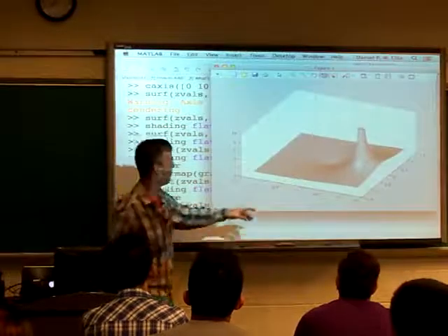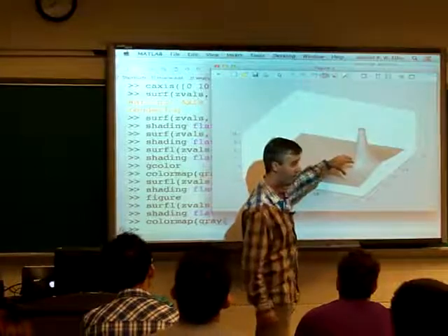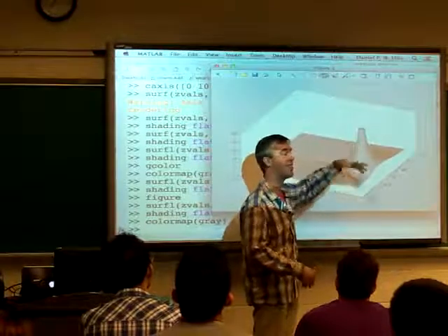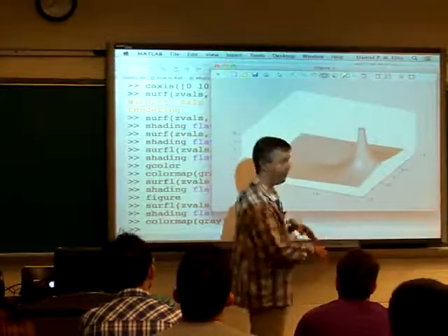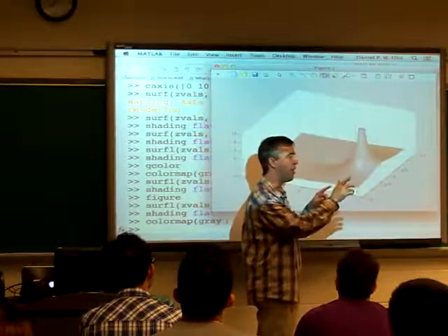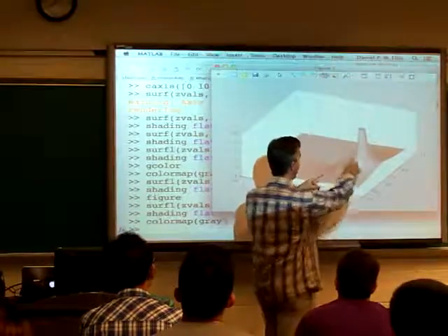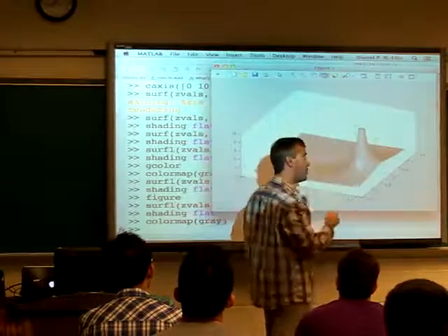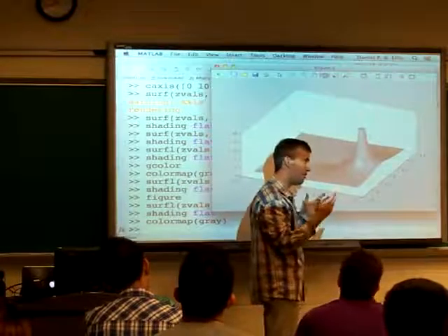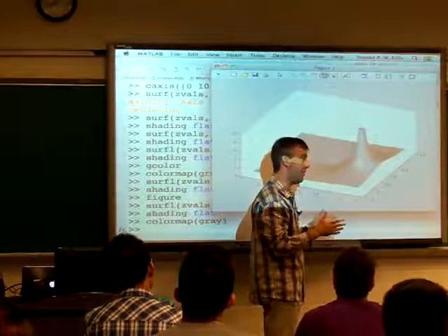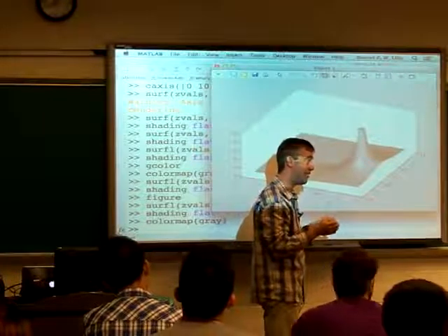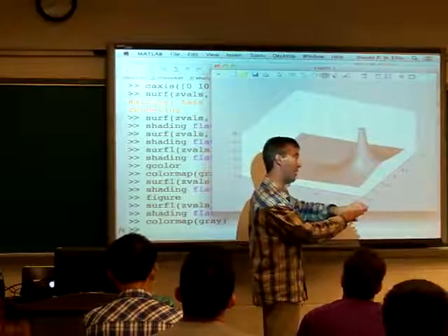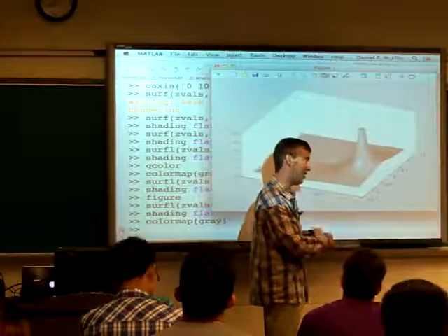It's just that outside of the region of convergence, the inner circle, 1 over 1 minus lambda z to the minus 1 continues to have a nice, continuous, well-behaved function, but the z transform blows up. And the other function, which I haven't plotted, would be this interior part and then blowing up everywhere outside. So you see the two, g1 of z and g2 of z, have different values. They have different values for every value of z. But it just happens that the convergent values match one another at the boundary, which is this z equal lambda radius.